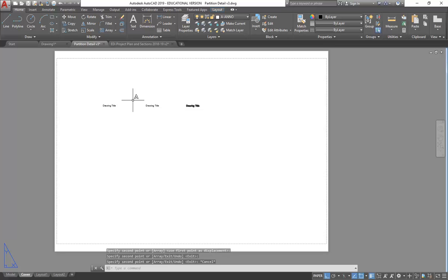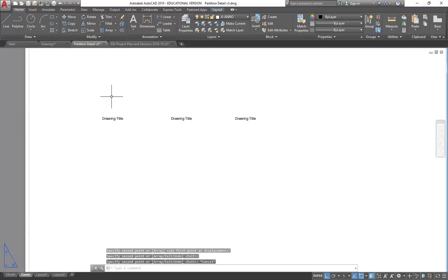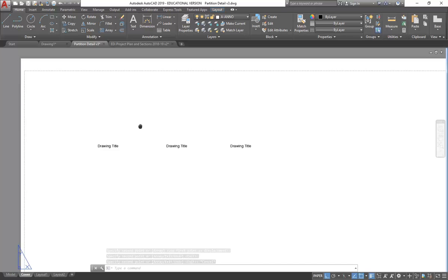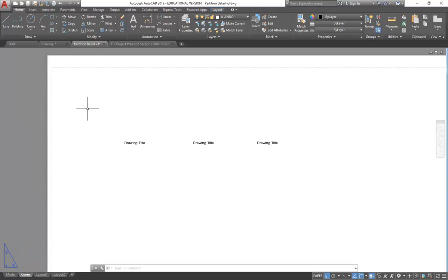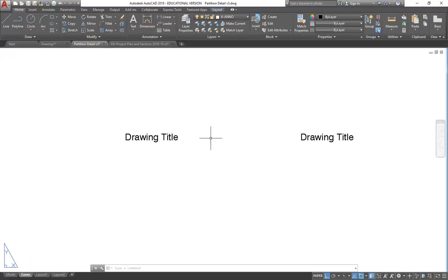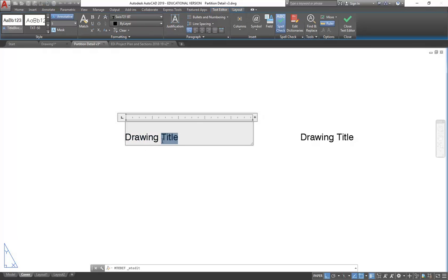a few times. And so what sorts of things do you think you'd want in your drawing list? Just before you even get to the point of knowing the names, what sort of categories do you think you'll want? Yeah, so what would that be? That's right. You want to think about how you're sorting it first. You definitely want the drawing name, and that's what those things would be. But before the drawing name or the drawing title, you'd want to have the thing that you use to sort your drawings, and that's generally going to be your drawing number.